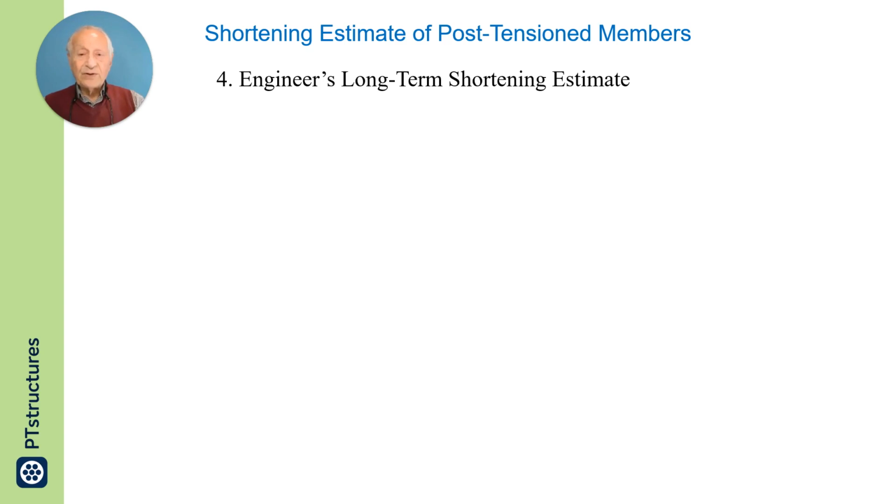You need to know the shortening during the design time in order to evaluate the details of connection of the post-tension members to their supports, walls, and columns.